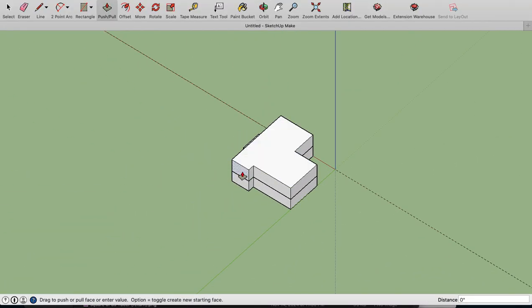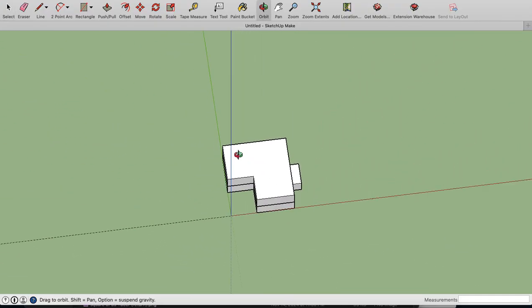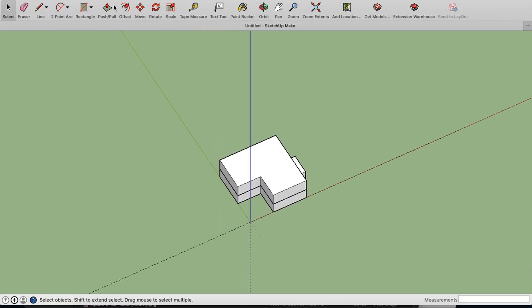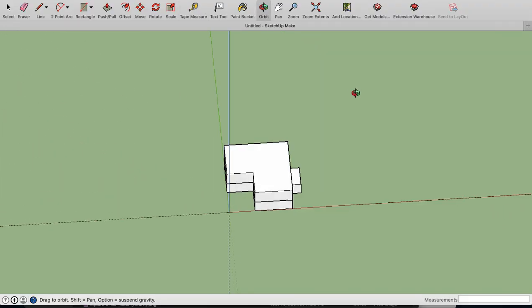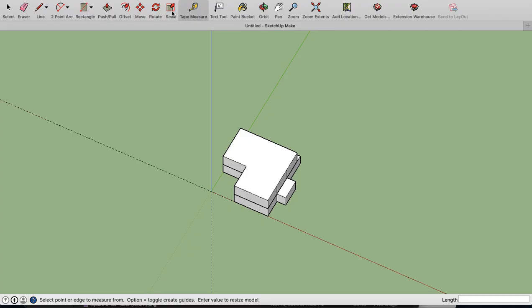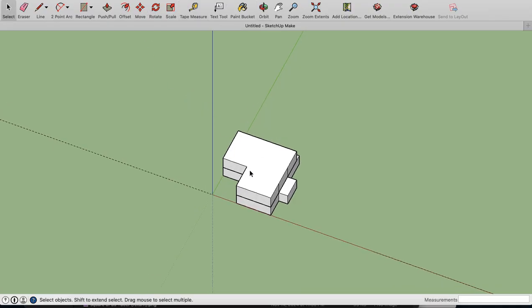Say the bump out was there, and then we bump it back in here. So on the ground floor, we'd have that 46 by 44 or whatever it was, and on the upper floor now, we'd have a building dimension in the horizontal that is 40, and the building dimension in the vertical that is also 40. All right, so as you can see, our building dimensions can change per story depending on how we're calculating them, depending on what we're designing.